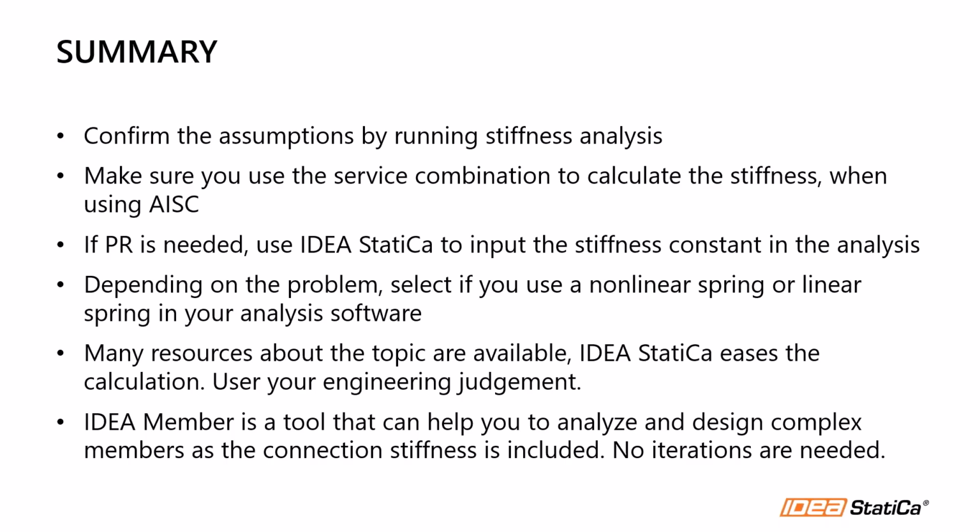Takeaways: you can confirm the assumptions by running stiffness analysis, confirming your connection or joint assumptions, right? Second takeaway: make sure you use the service combination to calculate the stiffness when using AISC. If for some reason a partially restrained connection is needed, you can use IDEA StatiCa to input the stiffness constant in the analysis software.